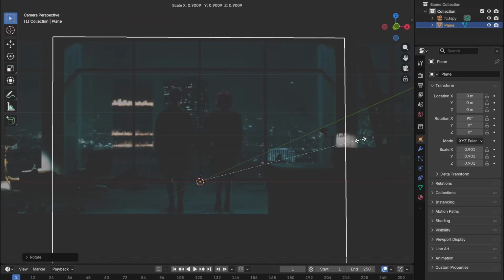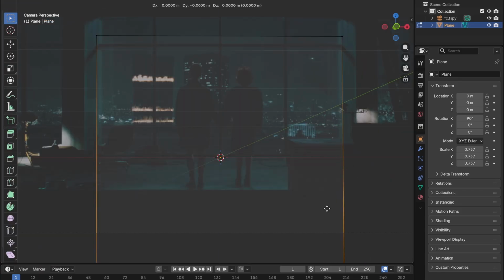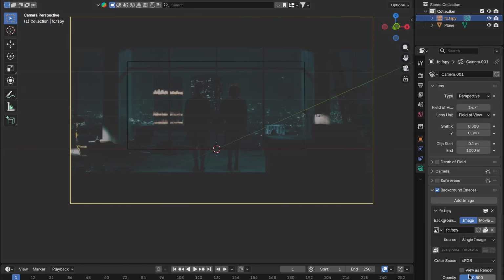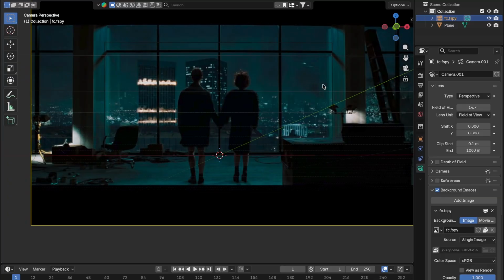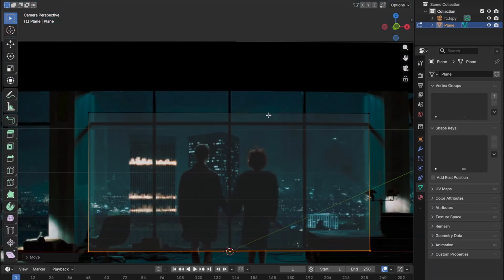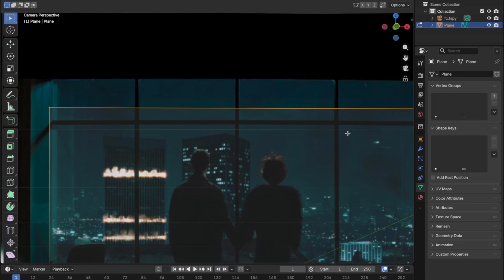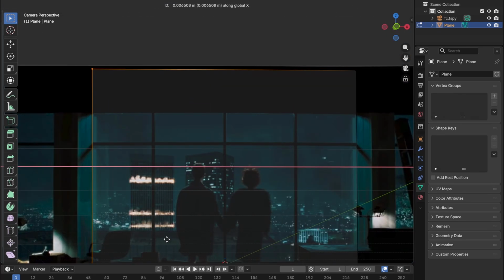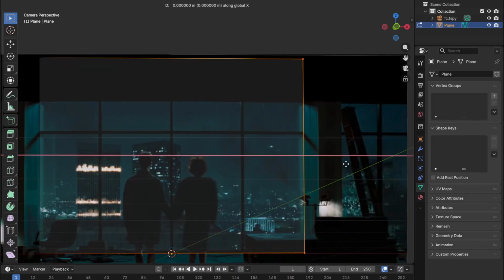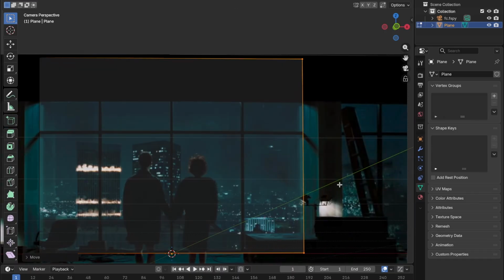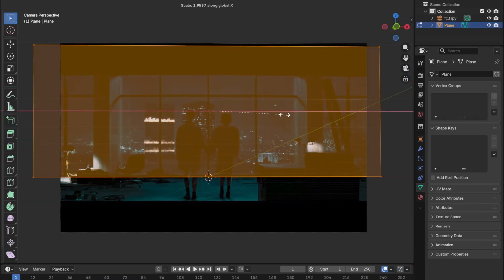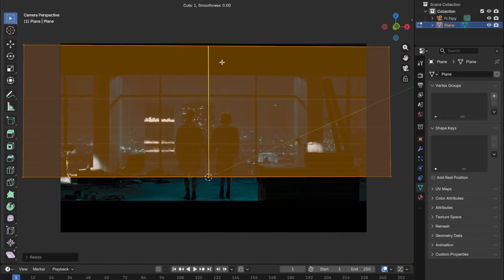We will immediately create our plane, rotate it and align it with our columns. The bottom edge we will place on the boundary of the window on the floor, and the top edge we will temporarily raise a bit higher and later decide where our ceiling or our roof will be. The left and right we will also align with our columns, meaning where the central part of our window ends. And after that we will expand the entire plane on the x-axis, again beyond the frame limits, and add our first edge loop.